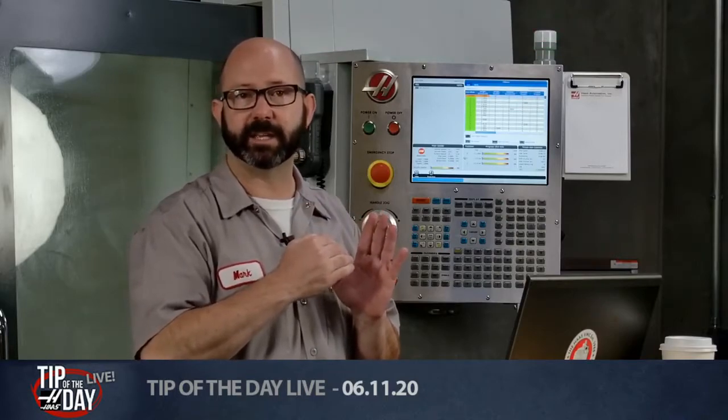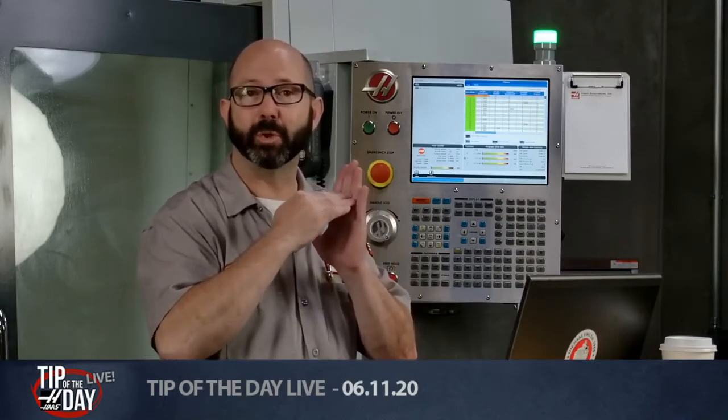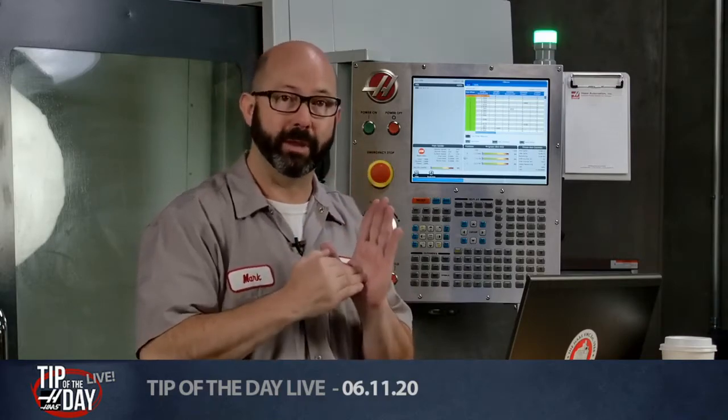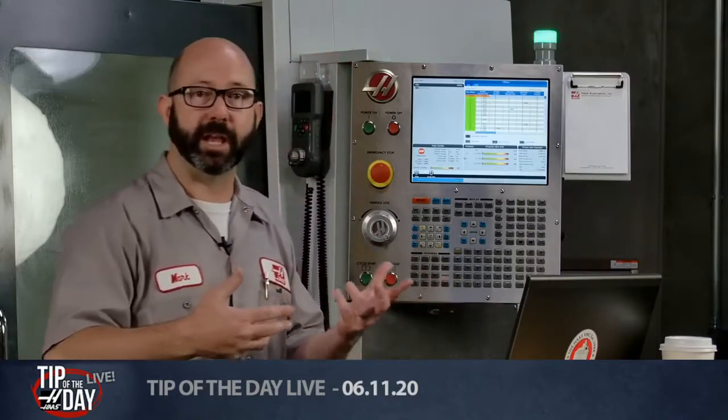That's super important for this reason, because when you go to the tool offset page and you press origin to wipe out all of your tool offsets, it's going to ask you at the bottom of that list, hey, do you want me to wipe out all tool offsets or wipe out all tool offsets except probe? And because we told the control that it's a probe, it's not going to allow you to wipe it out unless you manually go in there, go down to that tool offset and origin it out. It's not going to let you do it.